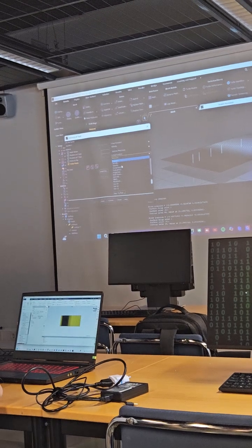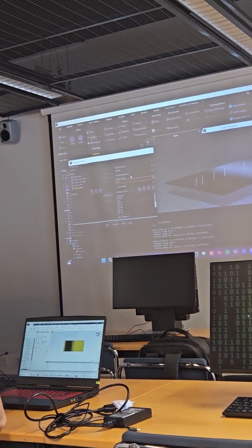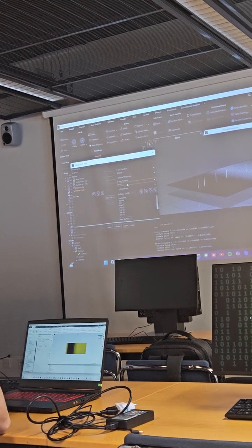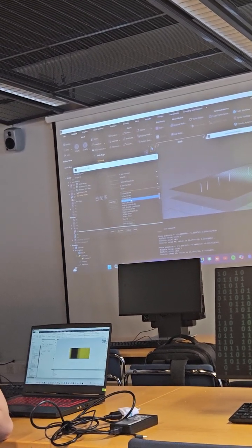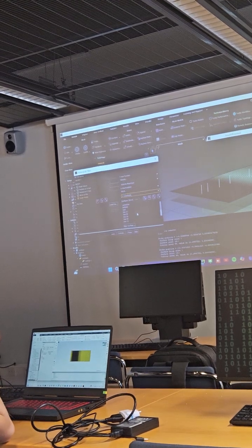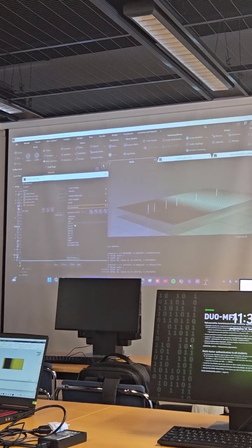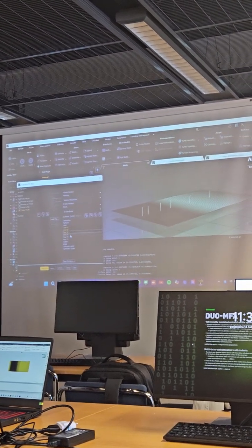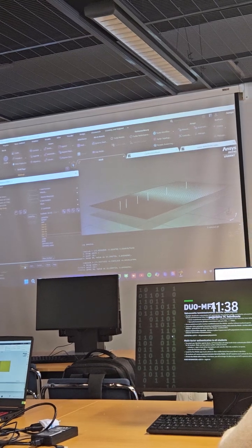So instead of pressure, I can choose mesh, and in mesh you have the x, y, and z coordinates. If I select that, then I can select the surfaces. I want all these lines I created, from line 01 to line 15.